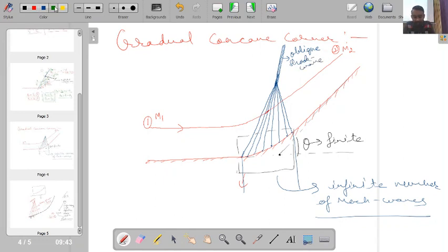And you will be finding that a streamline which is passing through this oblique shock wave will ultimately become parallel to the streamline which is passing through the series of shock waves, but above this point I will be having nothing but discontinuity in the variation of property. So suddenly within this oblique shock wave region, my Mach number has transformed from M1 to M2, and flow direction has changed from this horizontal direction to this particular direction, which is aligned at an angle theta. Okay, so in this region which is sufficiently away from the wall, I am having nothing but sudden variation in the properties, whereas the region which is very close to this particular boundary is actually gradually changing, and in this region I am having nothing but the gradual variation of the property.